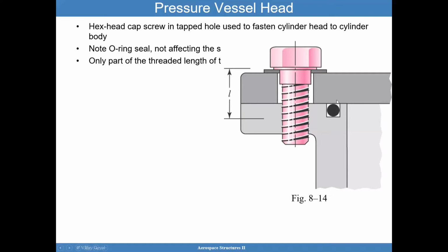The secondary O-ring, which should act as a redundant O-ring, may in fact not be effective as well. And so it's important to understand that your analysis should consider all combinations of things that could go wrong in terms of tolerances, thermal conditions, pressure conditions, and preload, making sure that preload is maintained during the application.